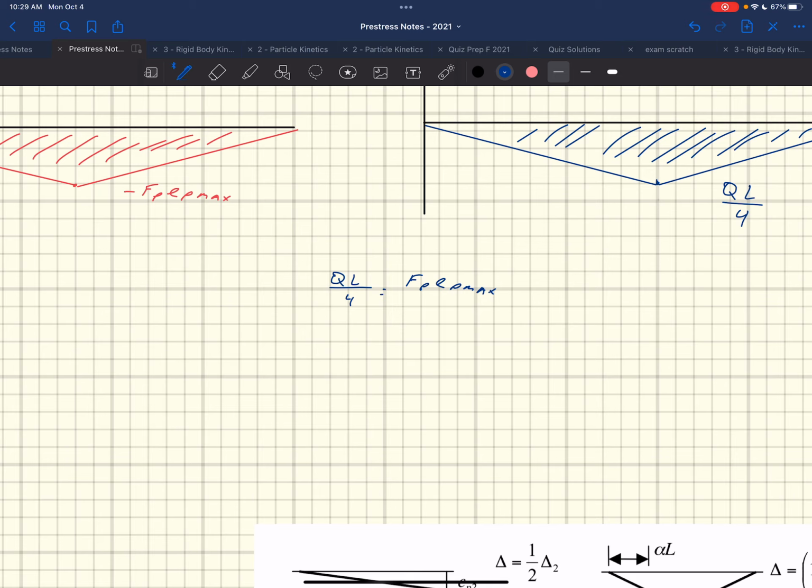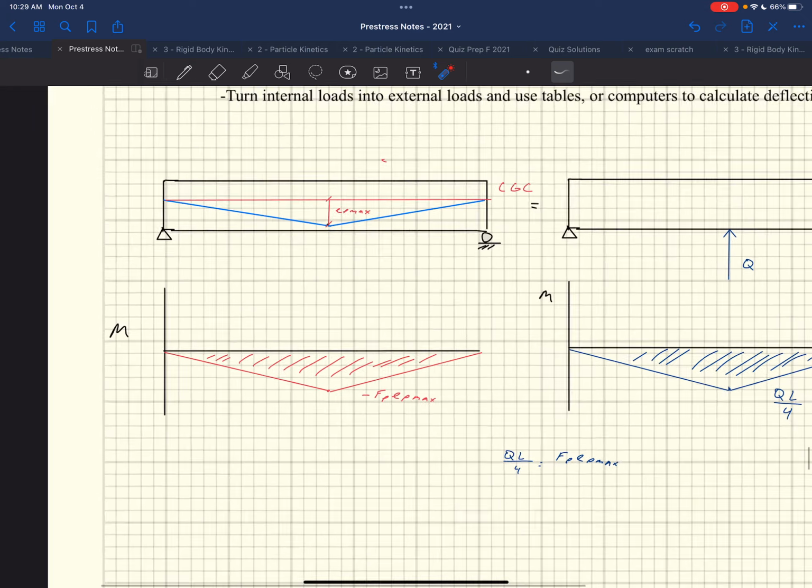The only time we ever consider the vertical component, where there's a component like this and a vertical component like that, is in shear design. In shear design, there's one of the variables and one of the methods, and you'll see it, that gives you a little bit of a boost to account for the fact that the FP has actually got a little vertical component.